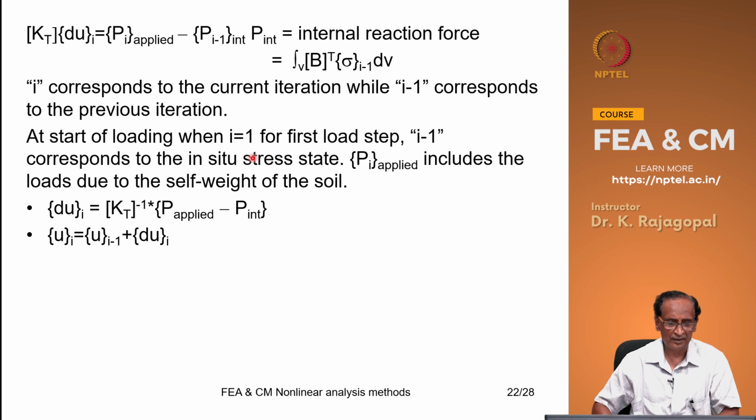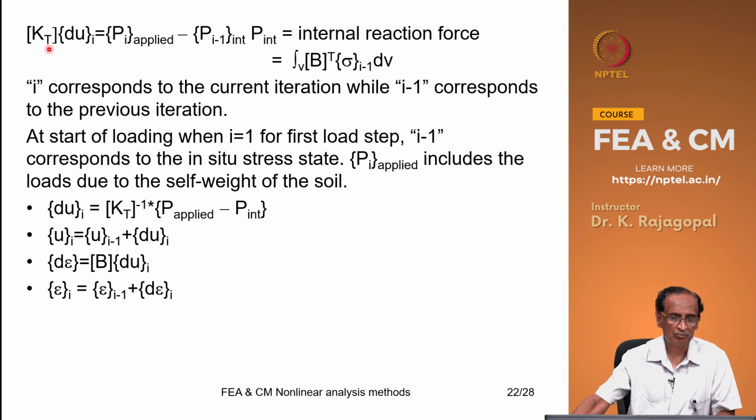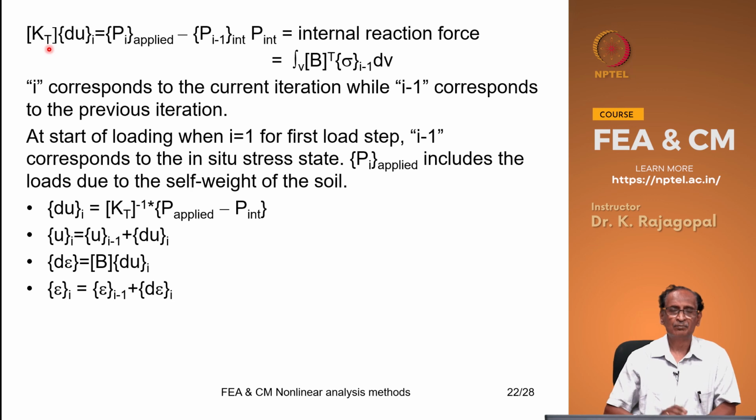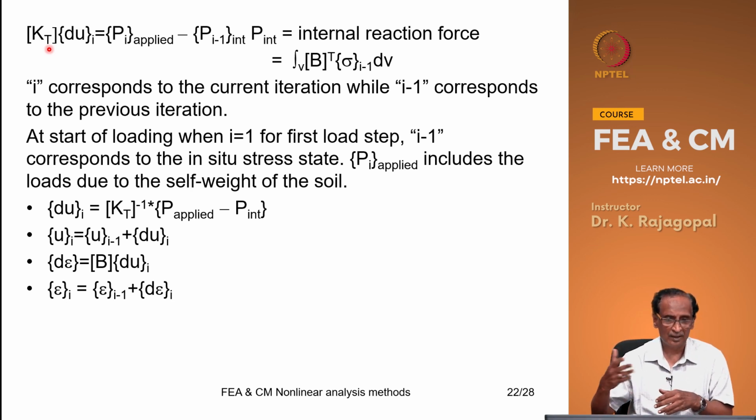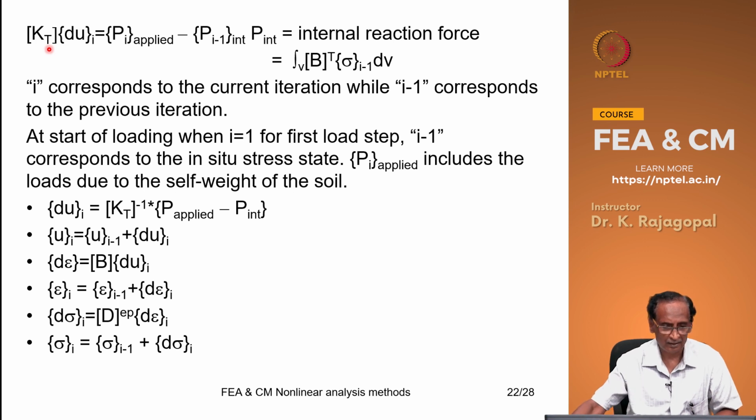So the only difference here is we are using this Kt instead of K. In the initial stress method, that K was remaining constant, whereas here we are updating it every iteration and every step, okay? So our stresses are computed